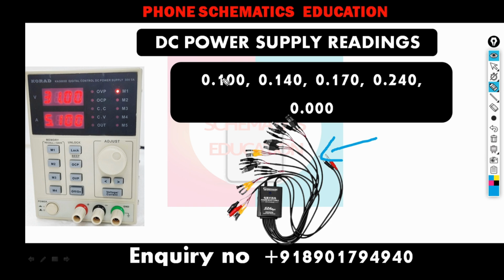So remember this point always. Some phones do not boot up on a DC power supply. Why? Because a single connector is compatible with around 150 plus models, but the circuit doesn't match each and every model. So whatever the model, only if the circuit is complete will it boot up. Otherwise, it gives you a fake result. So next,